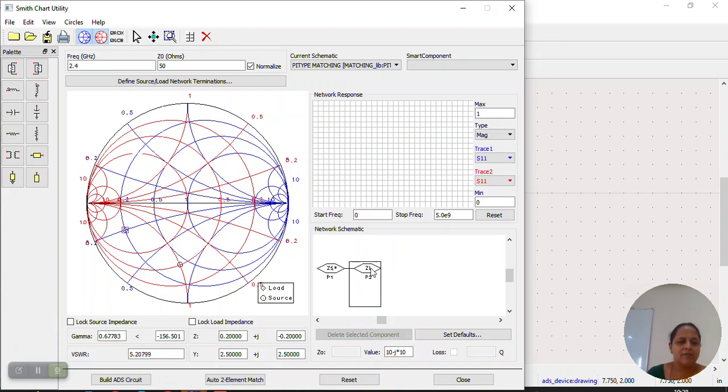Okay, so now I'll start from ZL. What is the second solution I can do is, I can go up in the resistance circle. So I'll take a series inductor, come up till this point. Then come down in the conductance circle. So coming down in the conductance circle, I can select, it's going up capacitance.